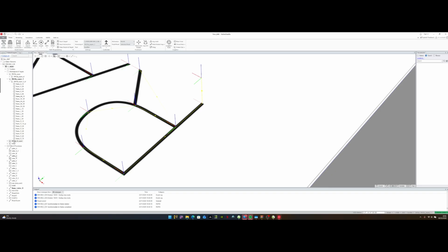If you come over here, back to home, paths and targets, go back to the letter that we're editing. Okay, it's saying target might not be reachable in current configuration. It's one common error that you're going to get. I will show you how to fix that error. But you move back here, you select the targets that you want. So this is the first target, second target, third, fourth.